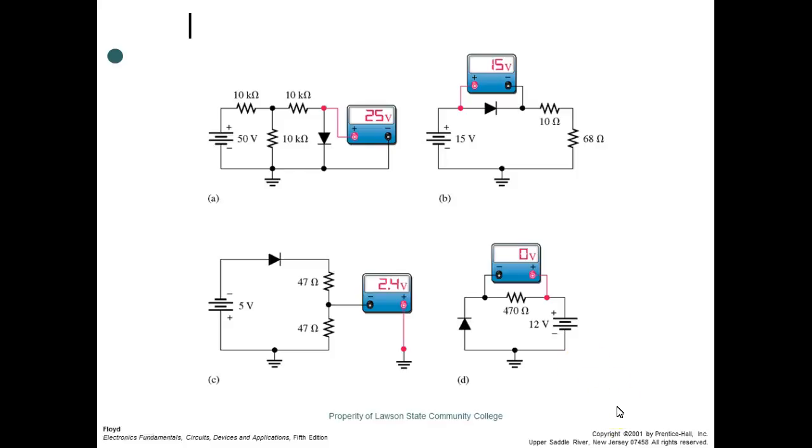So everybody okay on the approximation? So what approximations are we going to use? We're going to use second approximation. What's second approximation? That means for silicon, we're going to use what? 0.7 when it's forward biased. For germanium, we're going to use what? 0.3. That's not exactly what it's going to be, but that's close enough. When it's reverse biased, the 0.7 and 0.3 don't come into play.